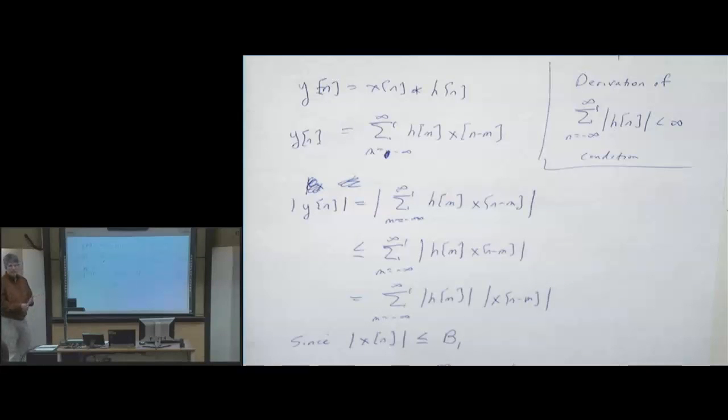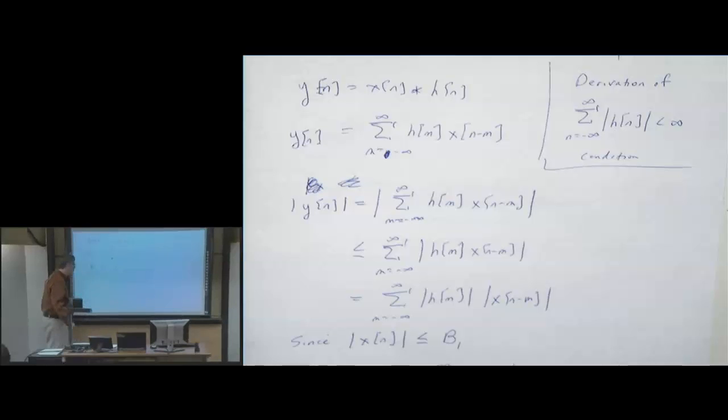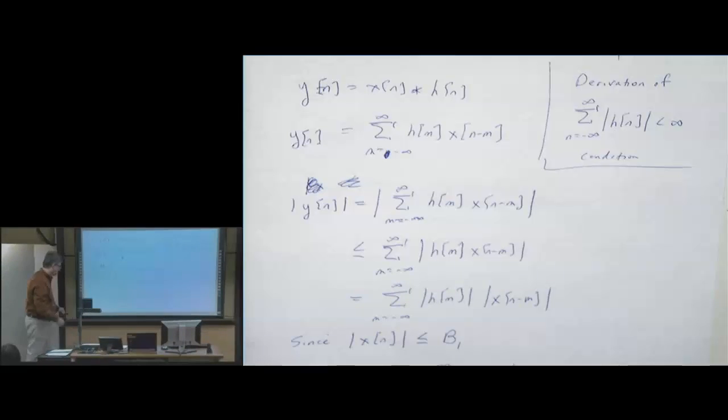Okay, again, we have an LTI system. The impulse response is h of n. The input is x of n. And the output y is simply the convolution of the input x of n and the impulse response h. We can write this as a convolution because it's what it is. If we write out the convolution definition, it's going to be the sum of little m from minus infinity to infinity of the impulse response h of m. We'll hold that in place, and we flip and slide x about h. So this is x of n minus m. Again, m is the placeholder of convolution. Little n is the outer discrete time variable.